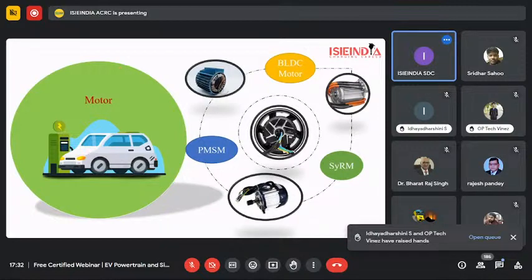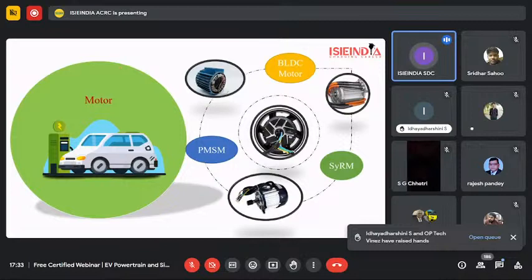The working principle of the BLDC motor involves a Hall effect sensor, and because of that Hall effect sensor, the rotor position is detected. Because of that detection, the controller of the BLDC motor gives information on which coil needs to be excited for rotating. BLDC motors have high initial torque, and because of that, these motors are used for traction purposes in electric vehicles.